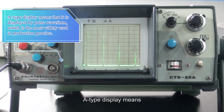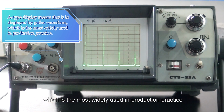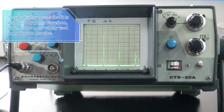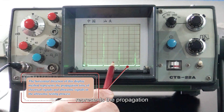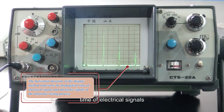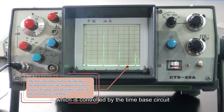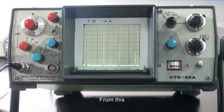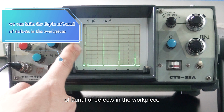A-type display means that it is displayed by pulse waveform, which is the most widely used in production practice. The horizontal direction of this display method represents the propagation time of electrical signals and ultrasonic signals in the ultrasonic test process, which is controlled by the time-based circuit inside the instrument. From this, we can infer the depth of the barrier of defects in the workpiece.